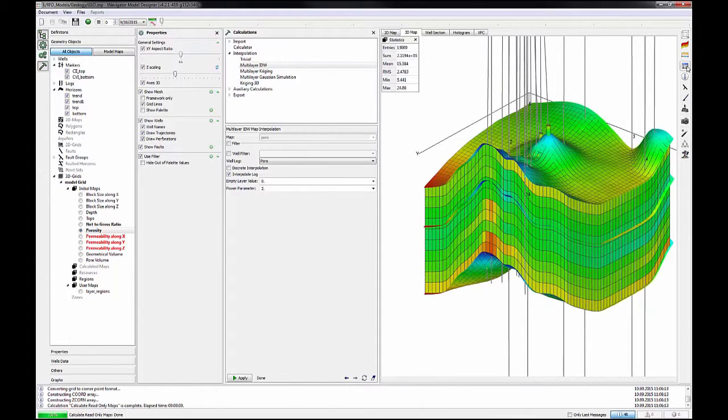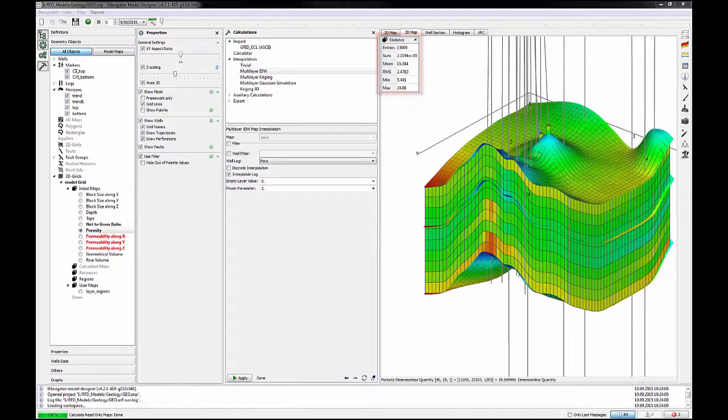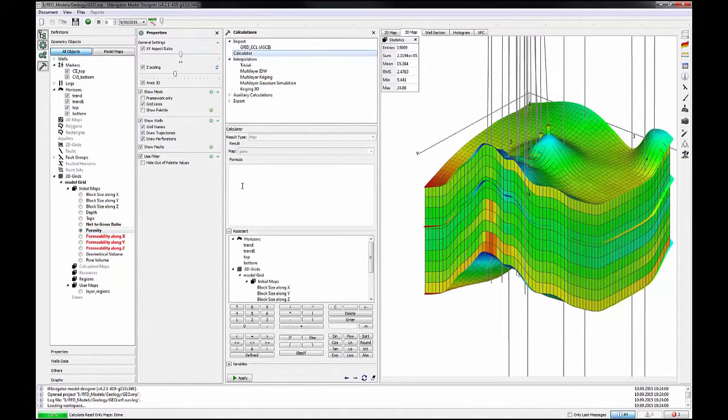Click on the statistics. As you can see, porosity from 5 to 25%. Now we're going to recalculate the porosity from percents to values from 0 to 1. In the Formula menu, just put the formula, then click Apply. Check the value by moving mouse on any grid blocks.